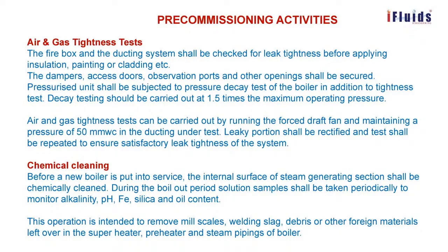That is, it's like a hydraulic pressure test. The maximum pressure should be 1.5 times the design pressure. That should be the pressure. In the decay test, whatever pressure is lost should be observed. If it is within the range, it is okay. Otherwise, we have to check the tightness of each and every flange.